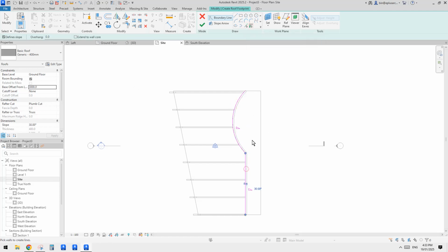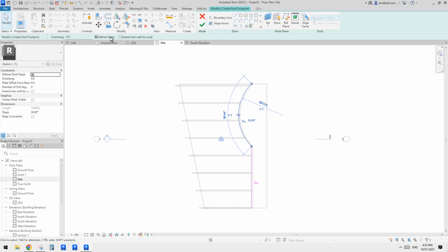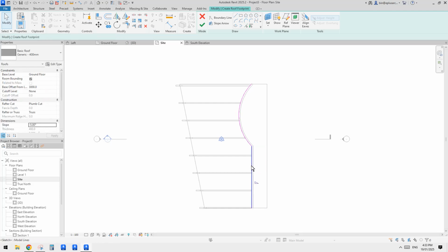We have some wall, so we can pick wall, but the slope angle will be. So we can do this one because this wall is perpendicular with the direction of this roof. So we can actually use this one. But we might need a negative slope. So maybe we can do that. So uncheck this one because we don't want to have slope on this one. So I'll type -5. So maybe I'll just use 4 meter because actually it will be good because we want this one to, the wall here is 4 meter. So maybe I'll just use 4 meter with a negative slope angle.